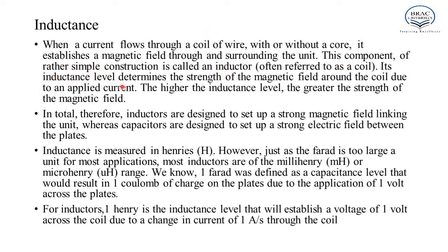Its inductance level determines the strength of the magnetic field around the coil due to an applied current. The higher the inductance level, the greater the strength of the magnetic field. In total, therefore, inductors are designed to set up a strong magnetic field linking the unit, whereas capacitors are designed to set up a strong electric field between the plates.